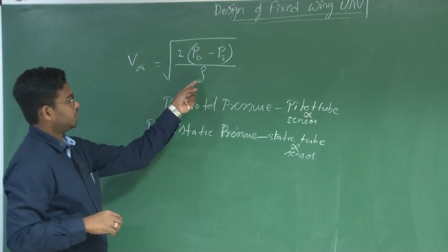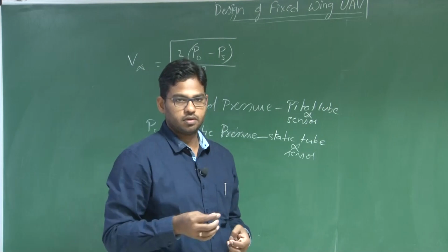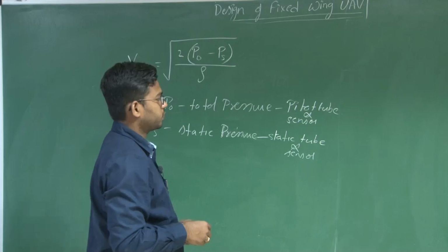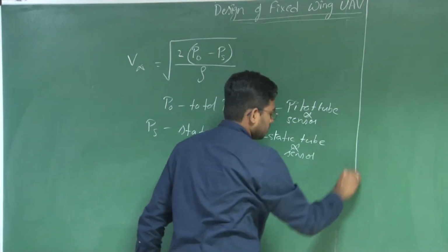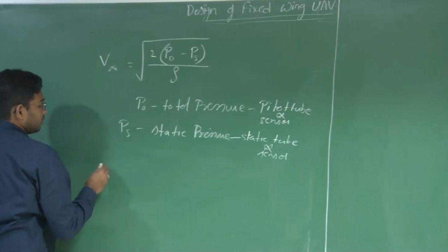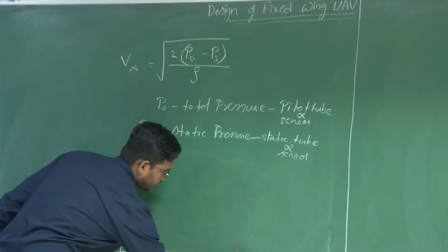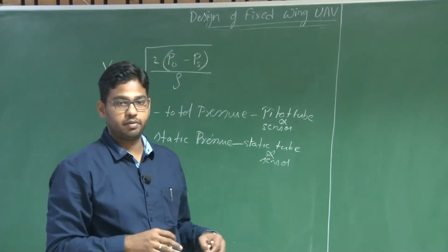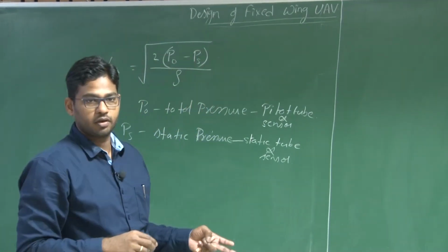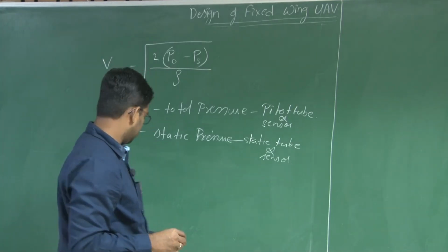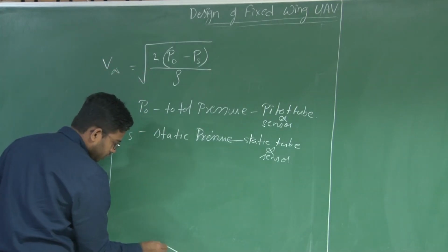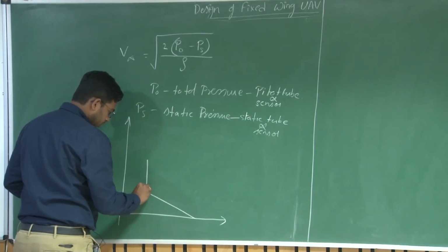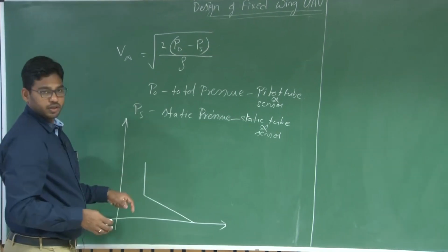And to know the density at that particular altitude, we derived the equations for standard atmosphere, where we observed there are some altitudes at which the temperature changes with altitude, and the pressure and density also change. The standard atmosphere is a plot that represents the variation of temperature with altitude. So let us limit ourselves right now to the first two layers.